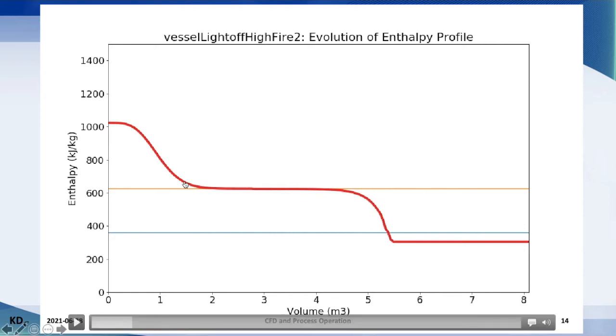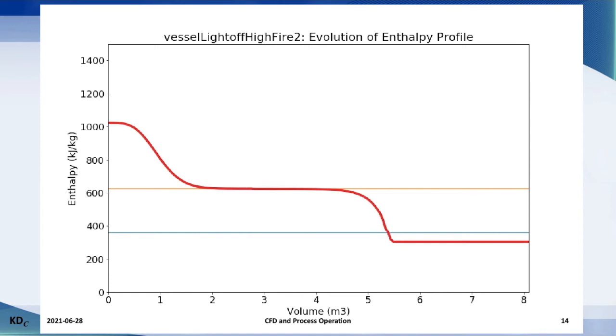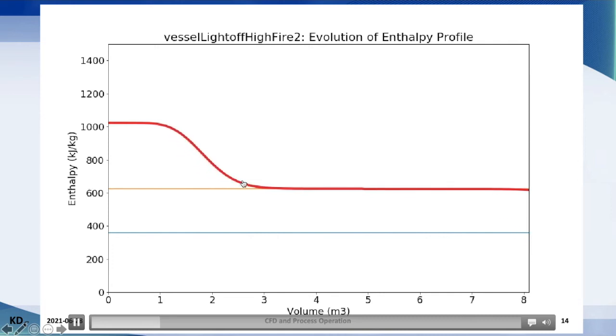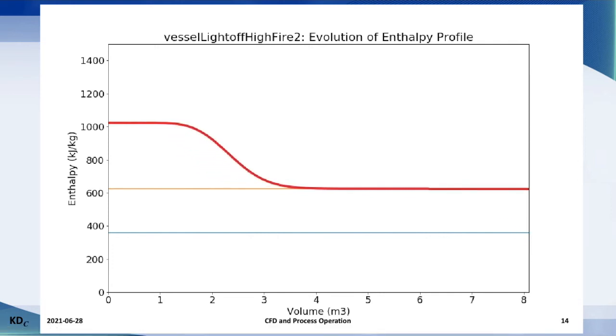Now the slowest step is where the superheated propane is warming up the bed. We no longer have liquid to push out, it is just vapor, but we have to warm up the bed from 57 Celsius up to our final temperature of 210. And that's what this long, very slow-moving ramp or temperature profile of enthalpy is representing. And we can see this pushes across the bed very slowly. And this takes about 3,000 seconds, so almost an hour, for that bed to warm up after all of the liquid has been displaced.